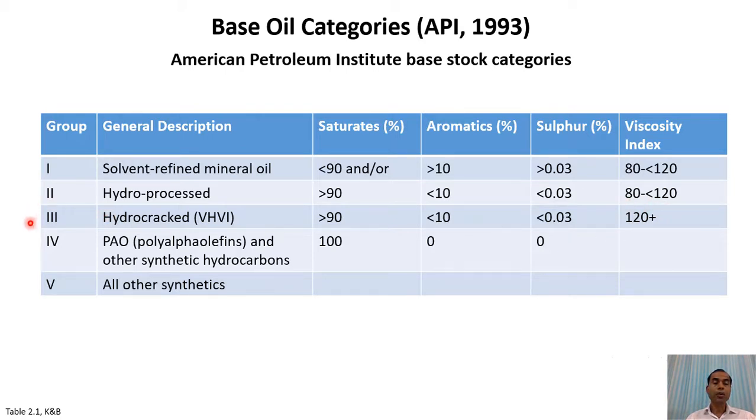So we can say that group 3 lubricants are the lubricants which have a higher percentage, or most of the carbon atoms, in paraffinic chains of branched chain type. So these are the purer form of hydrocarbons. Group 4 and 5 are actually synthetic oils.